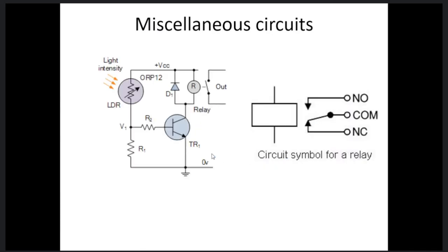And this is a light intensity sensor, like a simple LDR. Here, when you say smart lighting, it gets switched on automatically around 6 p.m., where you have very low sunlight. So this light intensity sensor, either a photoelectric sensor or an LDR photo resistive sensor, the main concept is the variation of resistance with the light.